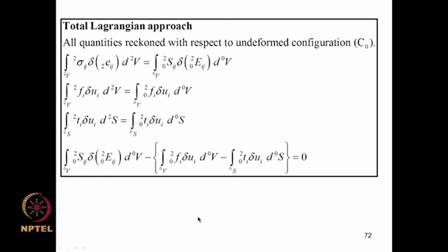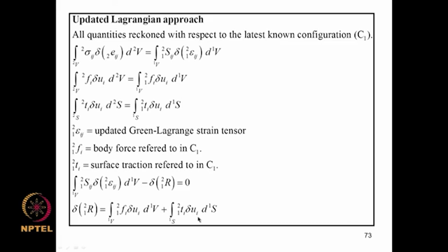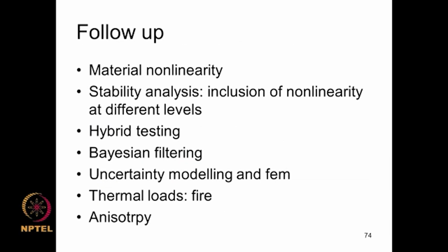Now, we developed the total Lagrangian approach and the updated Lagrangian approach, based on which we formulated the virtual work. These are the virtual work principles, and we formulated the structural matrices. So, this is a kind of a gist of what we tried to achieve during the course.